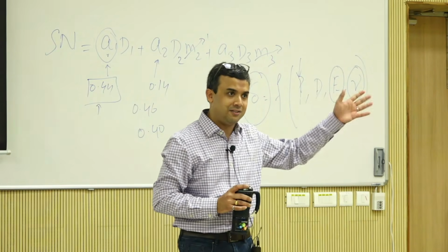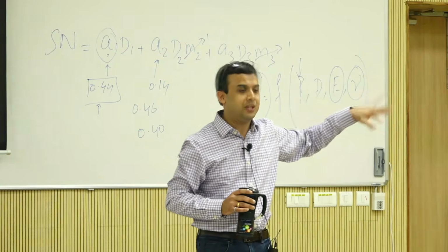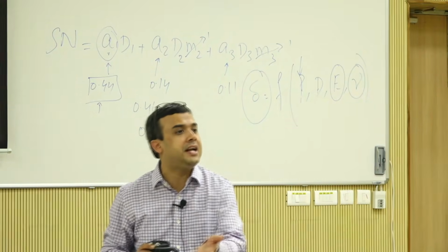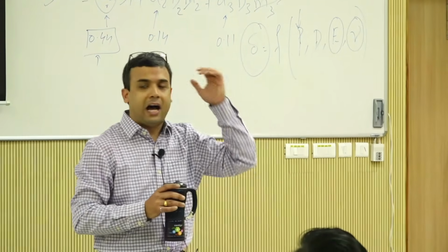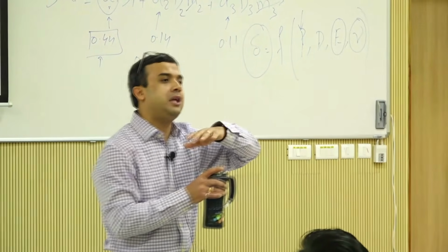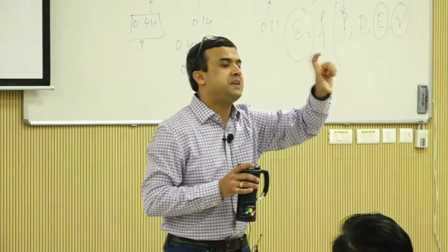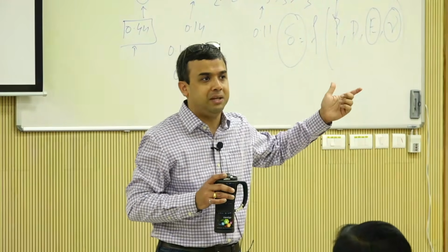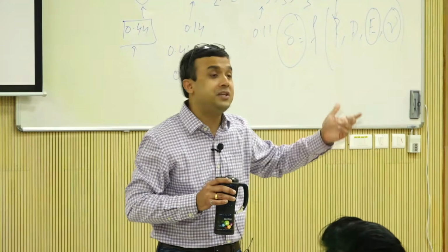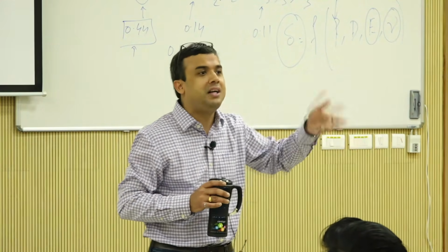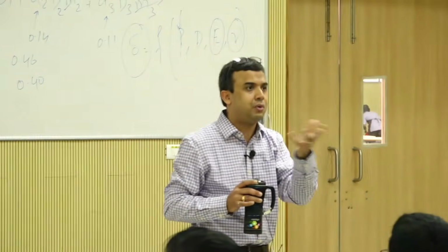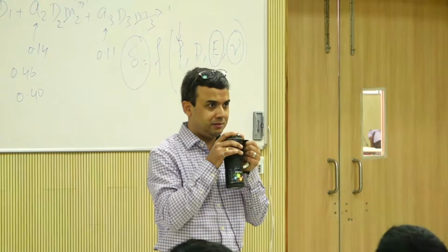Nobody has run all the tests. So that data is missing. And the data is not just missing, I mean, it's constructed data. Some of you I'm sure are familiar with construction practices. You specify 50 millimeters. The actual construction is sometimes 45 millimeters, 52 millimeters. I mean, it all depends, right? So that is going to change your response of the pavement. That's what back calculation is. Good?